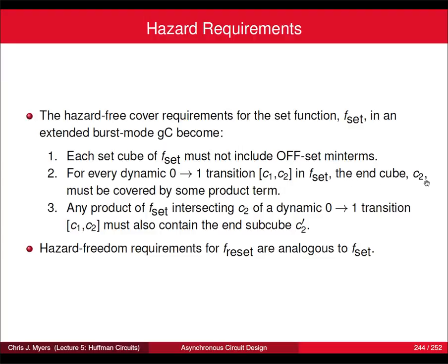The end cube, C2, must be covered by some product term. So this is essentially saying that C2 is a required cube, as it is in conventional. And finally, any product of F set intersecting C2 of the 0 to 1 transition must also contain the end subcube. In other words, you don't want a stack that is turning on and off during the transition, because that could create a dynamic hazard.